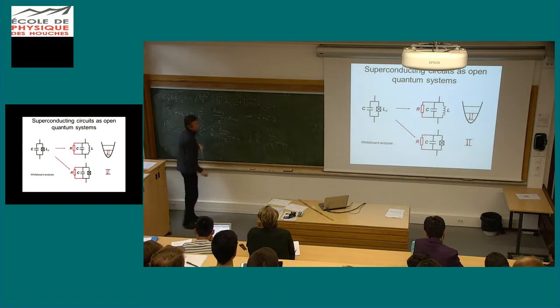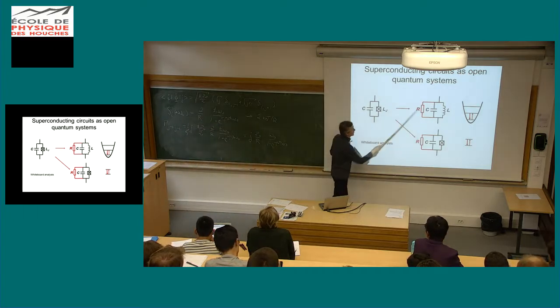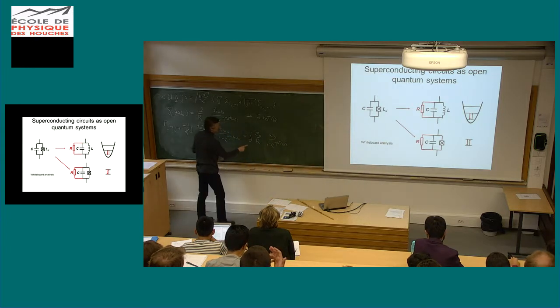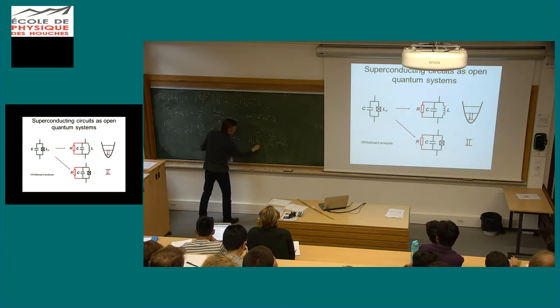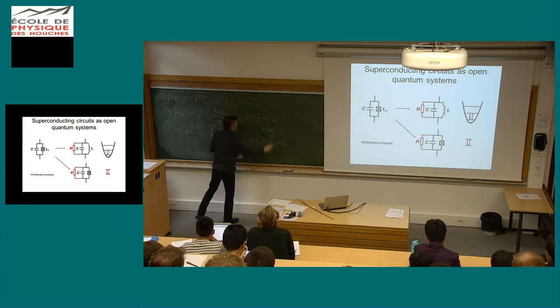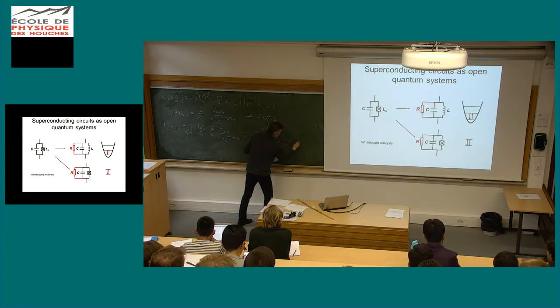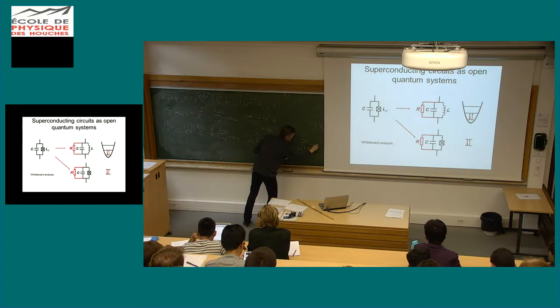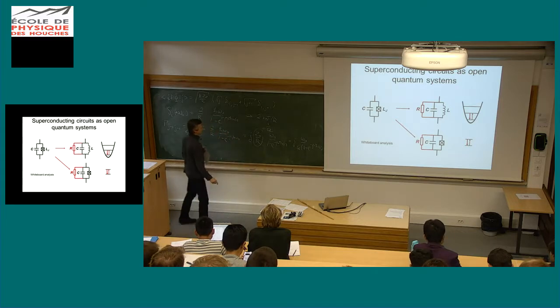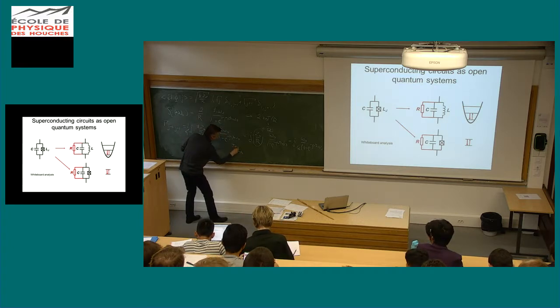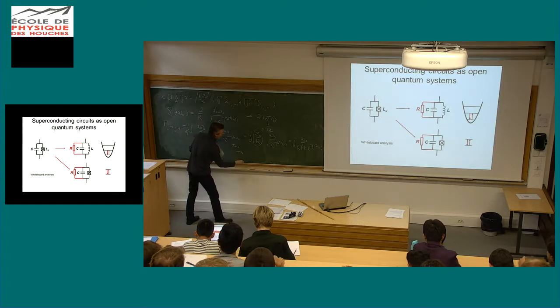Okay, but for this lumped LC resonator of this form, this here is 1 over the quality factor. So this is 1 over the Q of this. So we have a relaxation rate which is j times omega 0 over Q times 1 minus e to minus beta h bar omega 0. If temperature is low, T goes to 0, meaning beta goes to infinity, this goes to j times omega 0 over Q.